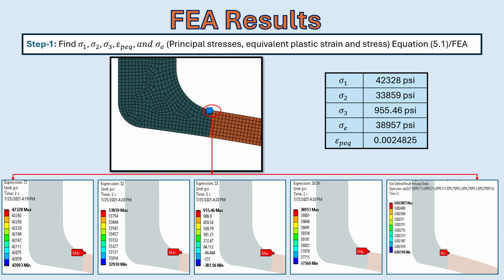Now we'll go through the steps one by one. Step 1 is to extract stresses and strains. Perform an elastic plastic stress analysis and extract stresses and strains from the FEA results. The effect of nonlinear geometry is considered in the analysis. The same model and material condition were used as example 5.2.3. Only pressure changes to 1.7p according to table 5.5. A critical node location, as shown in the example, is considered. I have selected the same node as used in the PTB-3 example.